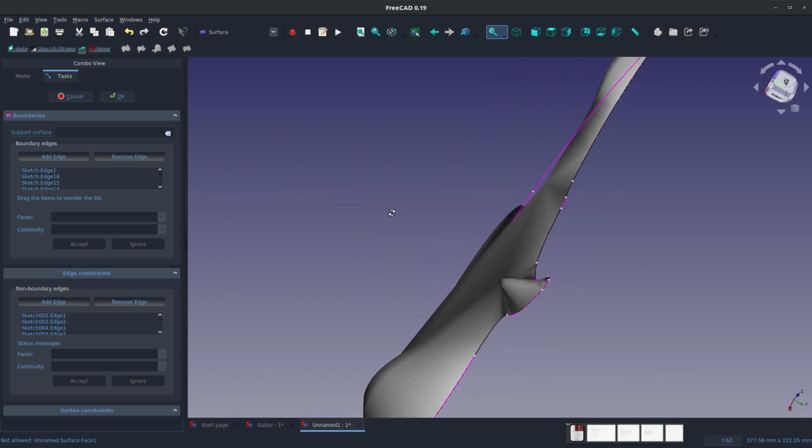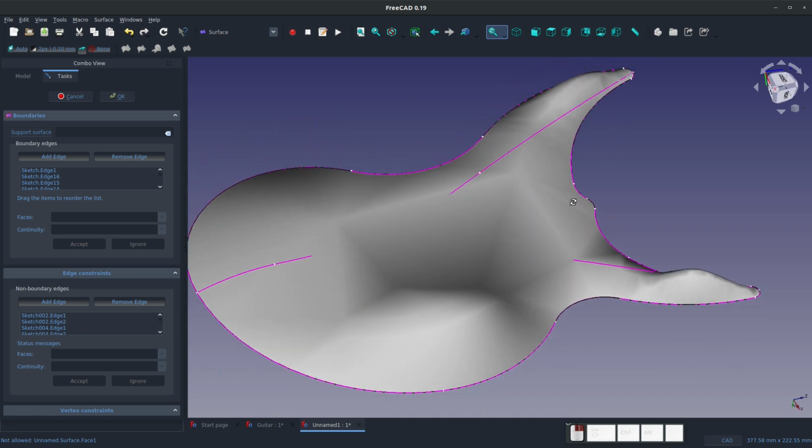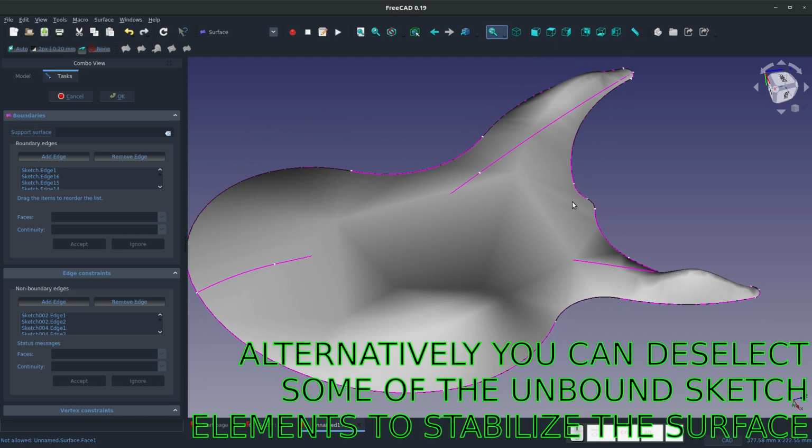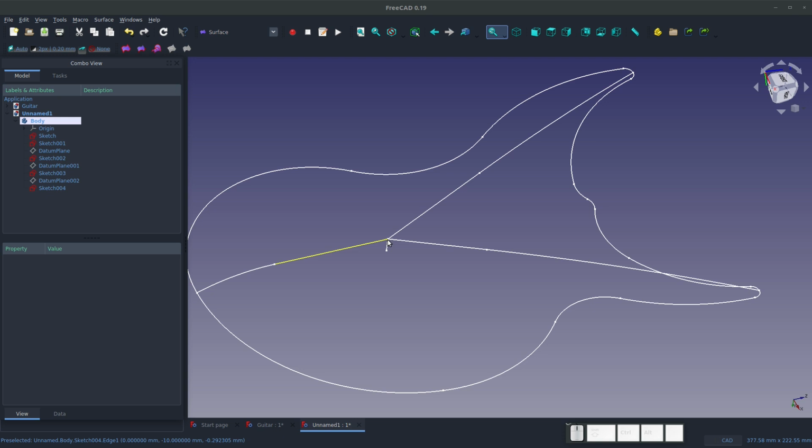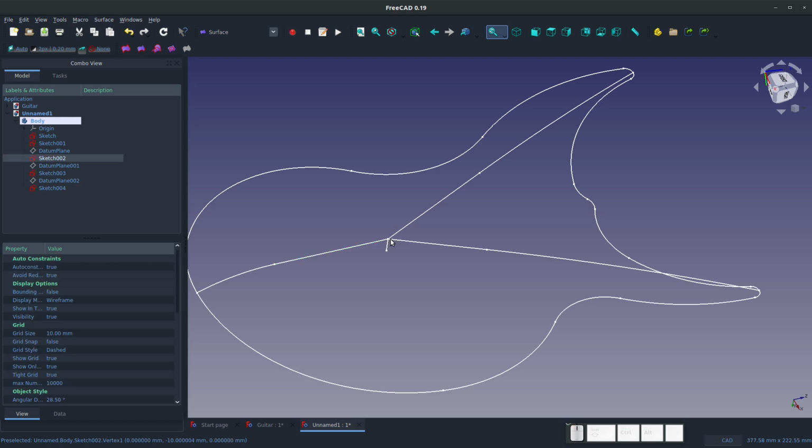And yeah, we need to add a few more controls to make sure that this is going to work the way that we want it to. So I could continue to add a plane that would send me a sketch from here to here and from here over to here, and maybe something going across here. So we can use the method that we've been using to help to fine-tune the exact surface we want, right? That's what I'm going for.